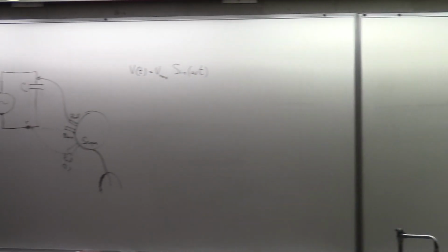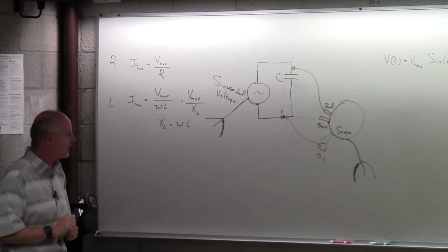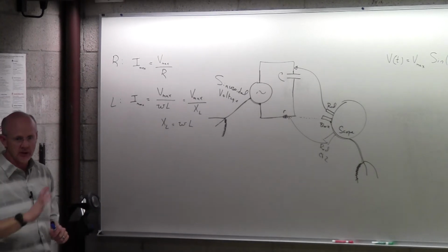And then you might as well go mid-range as long as we're talking about speakers. For that mid-range, I would put an inductor and a capacitor of a certain value, so I don't get the highs and I don't get the lows. I get something that's a balance between the two, which we'll do next here in just a second. And that's only if I did them in series. I could do something else in parallel, which would have other advantages too. So I probably would actually do that. But for this class, we're only going to do series. That's all we have time for. I think in your circuits class, you're doing series and parallel stuff.